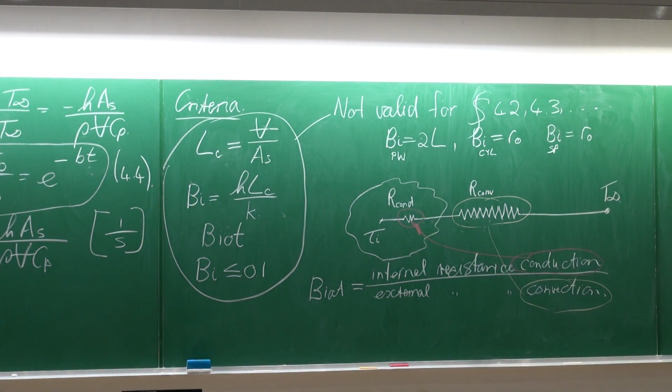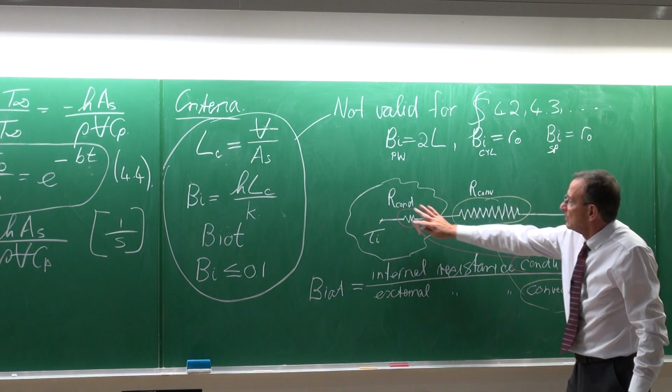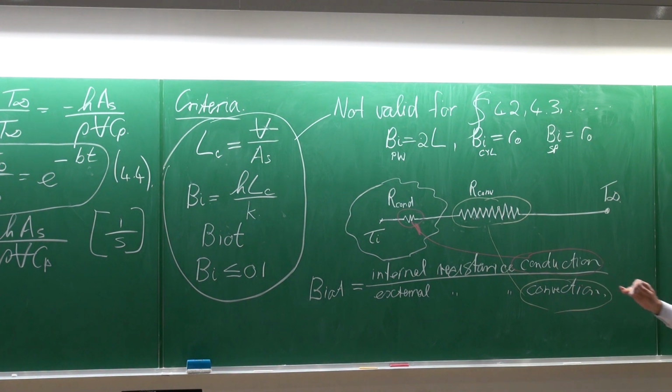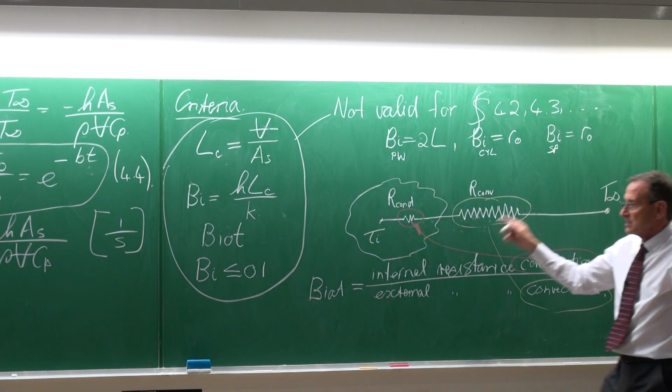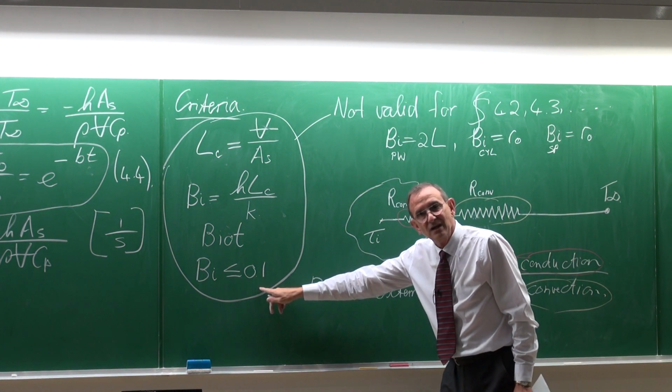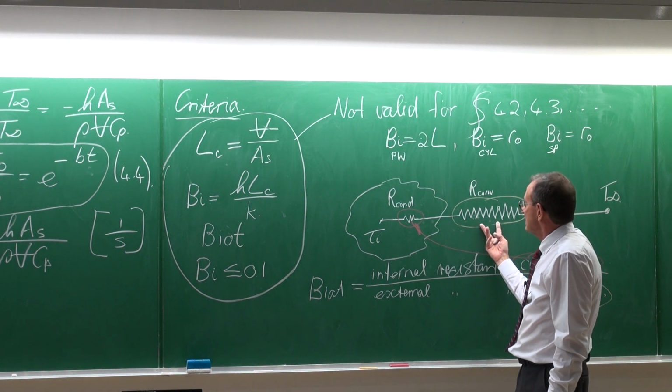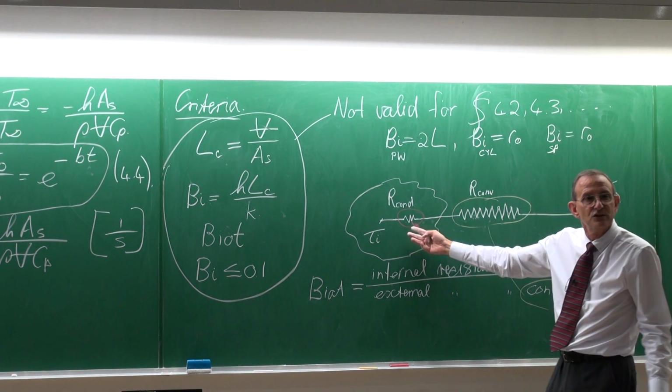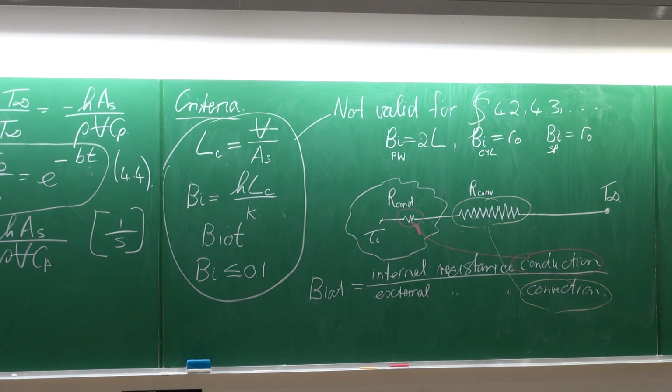And that is typically what this ratio means. It means that the conduction resistance is negligible in comparison with this resistance. So typically it's 10 times and more. So if this is 10 ohms in resistance, then that resistance should be 1 ohm or less. That is what that ratio actually means.